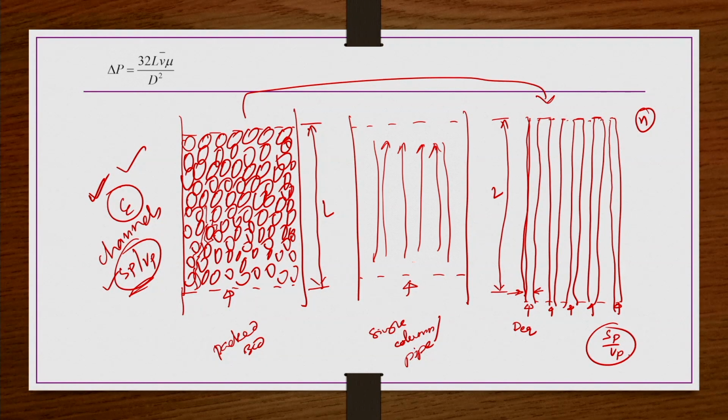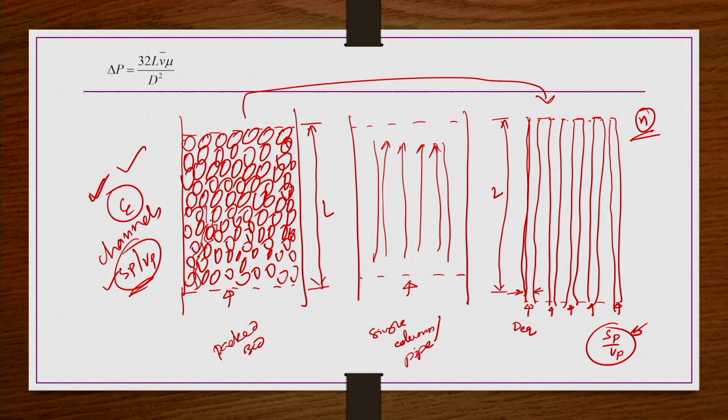And then the next one is the surface to volume ratio. Whatever the surface to volume ratio is for these n capillaries, that is the same as the surface to volume ratio for the packed bed. Okay. So, n should be decided such that for the bunch of capillaries, the epsilon and Sp by Vp are the same as, or equivalent to, those in the packed bed case. So, this n has to be found out. In reality we may think about it, but we do not need to find it out, let us assume this is n. Okay. So, this we are doing.